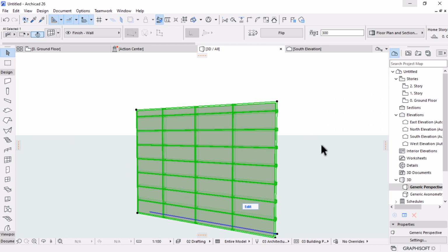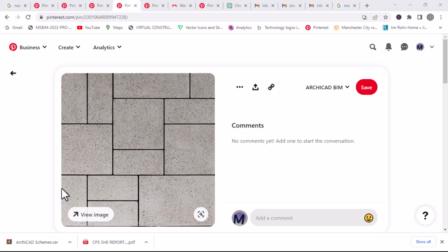We'll look into something now complex or a bit advanced in the next demonstration. To move on to the next pattern or style, this is more advanced than what we created before, and it's a pattern that has a lot of intricate shapes within shapes. So the best approach to look at it is we have rows and columns. That's the most basic thing to think of when designing this in ArchiCAD. That's how the curtain wall feature works.